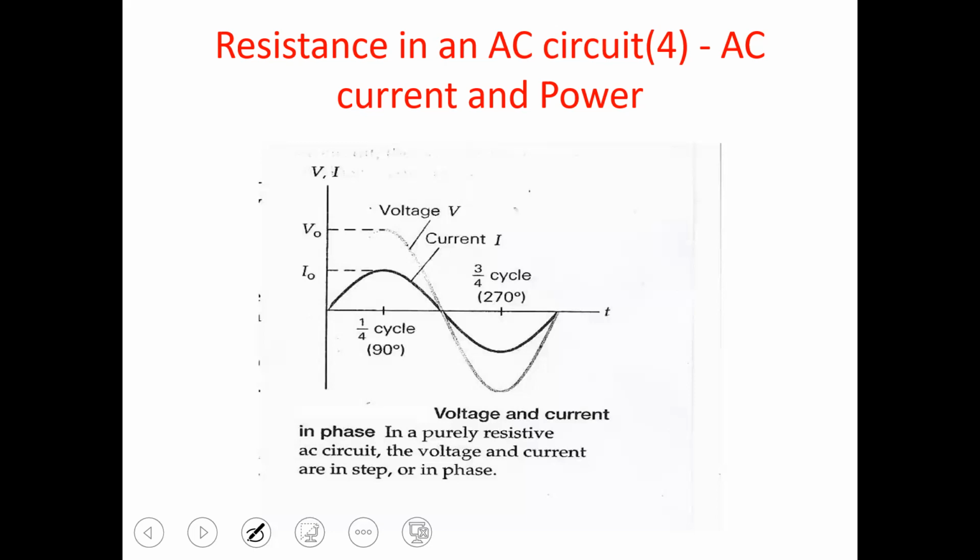If you put a direct voltage there, you will not have a steady output, because the transformer operates based on the rate of change of magnetic flux. When you put in alternating current, the current through the primary coil is changing, so the magnetic flux is changing, and it is that changing magnetic flux that will induce EMF in the secondary coil.